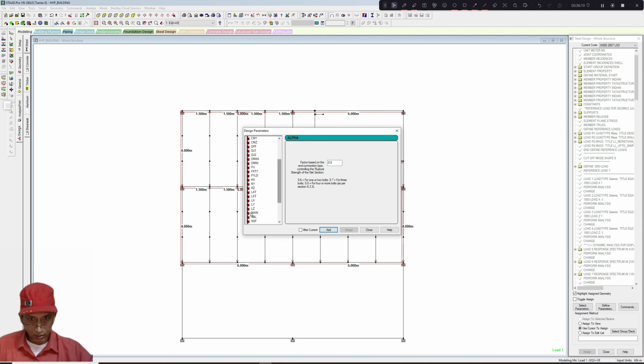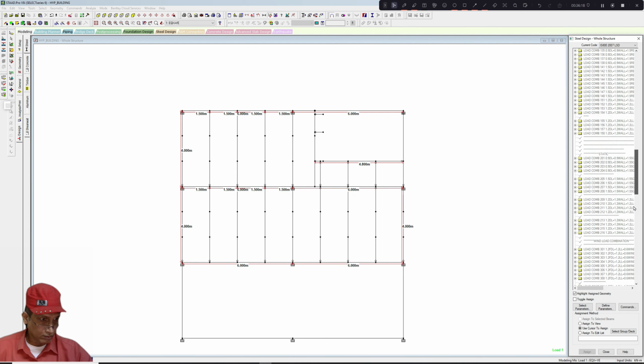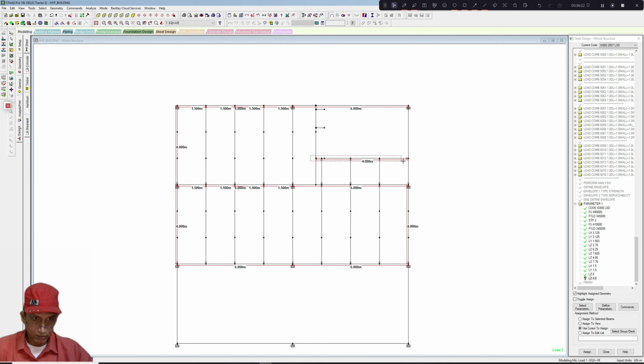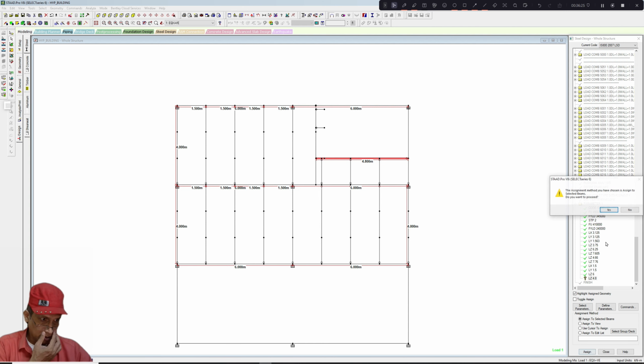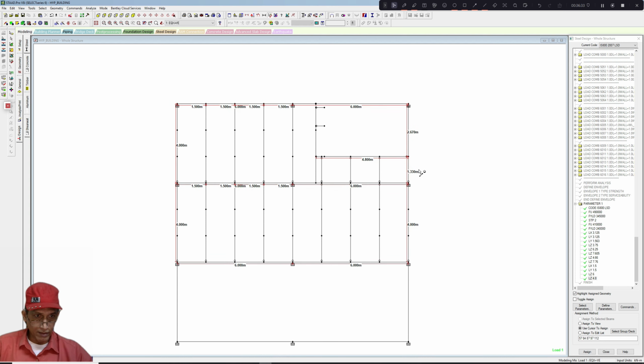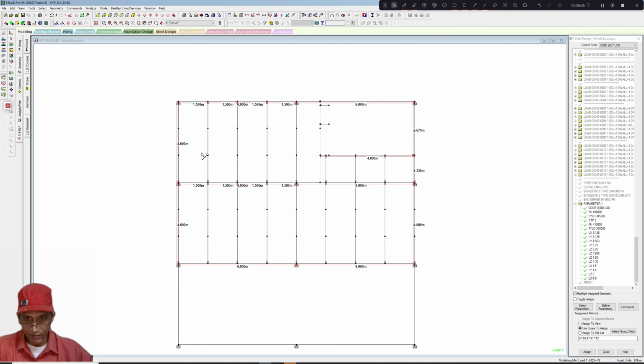Define LZ is equal to 4.8 meter. We are not defining any LX LY parameter for this beam. No distance will be taken itself. So LZ parameter we can define.